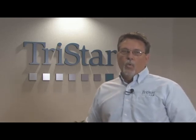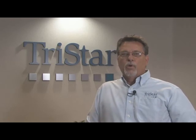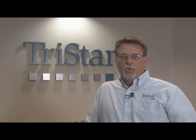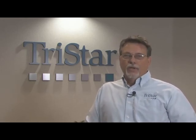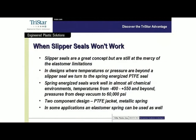So, when urethane seals won't work, when O-rings won't work, when chevron packings won't work, and then when slipper seals don't work, that takes us now into really the top dog, if you will, in the seal world, and that is spring energized PTFE seals. When temperatures or pressures or chemical environments are above and beyond what any of those other seal materials or geometries can accomplish, that's when spring energized PTFE comes into play. These types of seals can operate from minus 400 to plus 550, even up to plus 600 with some materials. We can operate in deep vacuum up to 60,000 psi.